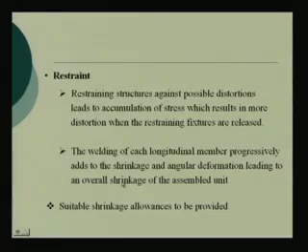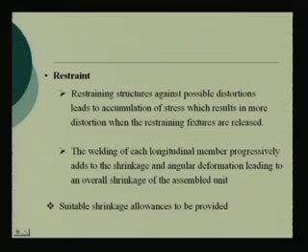There is another aspect of putting restraint, that means you do not allow the structure to deform, you put restraint. But as I have mentioned here, restraining structures against possible distortion leads to accumulation of stress, which results in more distortion when restraining fixtures are released.